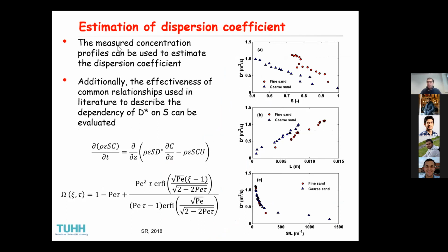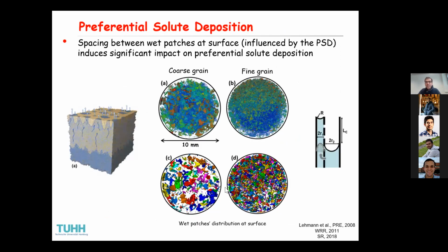But yeah, you can use this data, for example, to do the convection diffusion equation and calculate dispersivity in porous material, because now I have the concentration profile. This is, for example, the analytical solution of the convection diffusion equation. You can do it numerically and then fit that to the experimental data, get the dispersion coefficient, which is useful in many different fields. But I skip these things because the message of my talk today is something else.